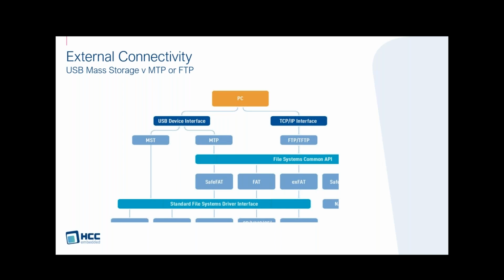This is why many cameras, video recorders and things switch off locally when you plug them into the USB, because they're running standard mass storage interface, and they don't want the possibility that you can crash the PC or crash the local file system, because you modify some key FAT entries in both systems at the same time, and they conflict. So the USB mass storage solution is good if you can switch off locally.